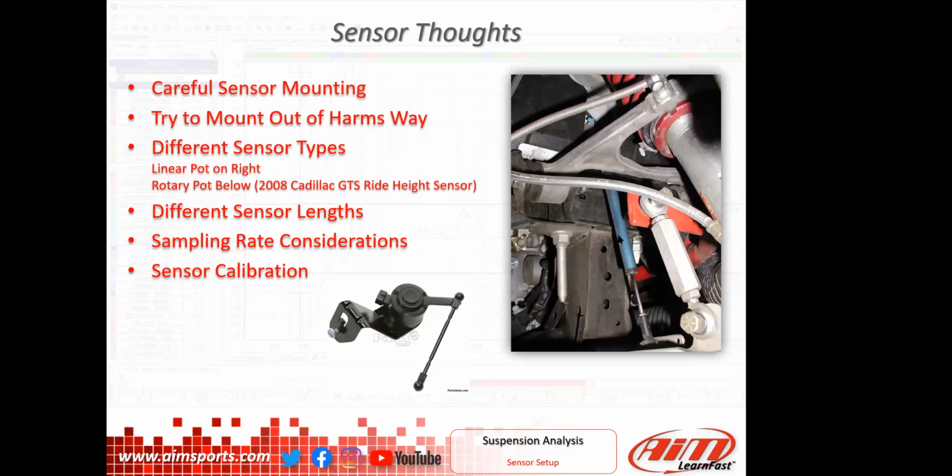And sometimes when you hit a curb, you get a super high rate of speed, many millimeters per second of travel velocity. When you're trying to move that entire big bulk of the body of the sensor, you can break it, you can bend the shafts, you can do some other things. So it's always good to mount the light end on the suspension arm and get a good idea of what's happening. Keep that in mind as well.